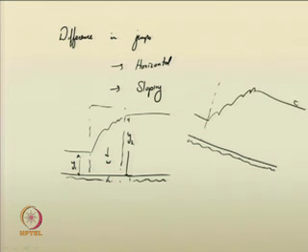If you take the control volume here enclosing the hydraulic jump, definitely the weight of water will be in the vertical direction, but due to a considerable slope, say the bed is having an angle theta with the horizontal, then there is definitely a component of weight in the direction of flow. So, that will also aid the flow and you cannot neglect that component.